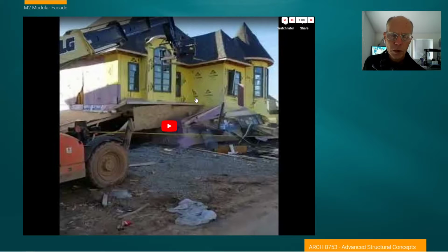Actually, in M1, it could be a curtain wall. It could also be a shear wall. But a lot of you labeled the sheathing as drywall or gypsum board. And moisture-resistant exterior grade gypsum board is used as a sheathing material. But what I caution you there is that it is not a structural material in and of itself, at least in some of the ways that it's rated. So pay particular attention to that.